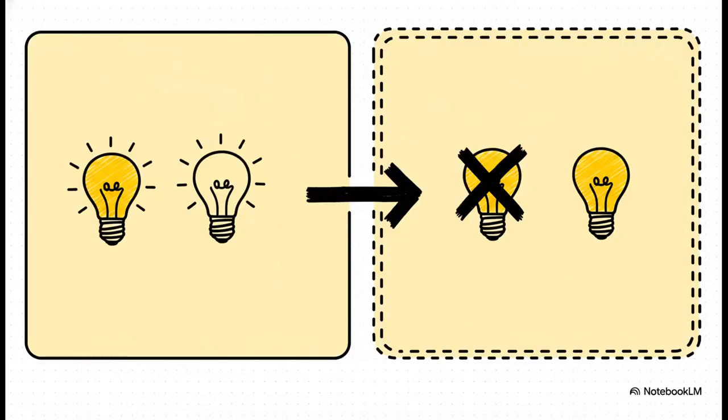You know what's really brilliant about these critical exterior indicators? The built-in redundancy. You are never just relying on a single bulb. Primary elements are normally set for use, but then you have secondary elements serving as backups. For the position lights, these secondary elements are armed backups. If a primary fails, the secondary instantly takes over. And for the anti-collision lights, a secondary element is selectable manually. It's a fantastic fail-safe system.